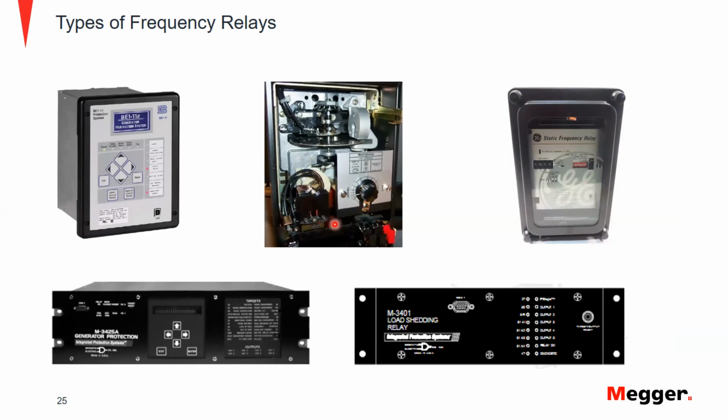I have tested a few of these old guys years ago. And then we also have the old static relay, which is GE, and these guys are still around as well. And then even some manufacturers are putting out their own load shedding relay, which is just specific for that particular application. So in general, the frequency element can come in all shapes or sizes, actually.